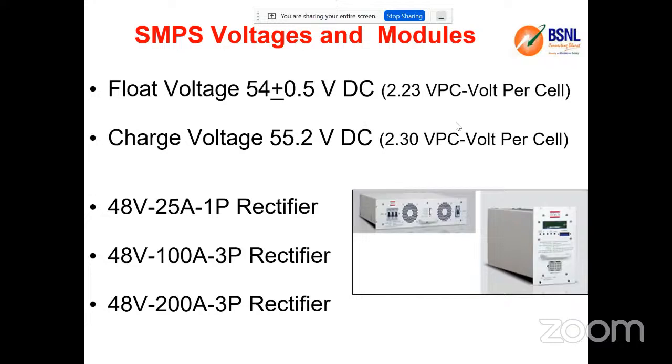So if you come to on road, then they will say it is a continuous transition. You should not have speed breakers, you should not have stops and starts, you should have only a single passenger. Every condition is like that. So on road, for 48 volt, we should maintain at least 54 volt. Then only the loss in the batteries, the transmission loss in the cables, and the regulation parameter are overcome. So finally, we'll get 48 volt.